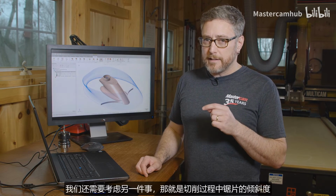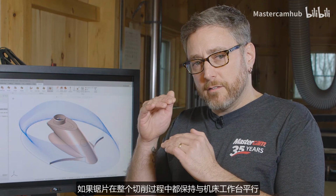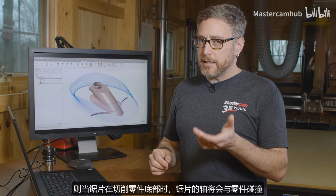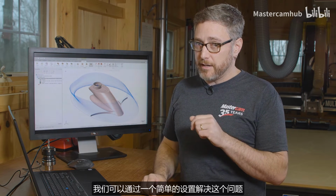There's one more thing we need to take into consideration, and that's the tilt of the saw. If the saw remains parallel to the table of the machine during the entire cut, then when it gets to the bottom, the arbor of the saw might collide with the part before it's able to fully cut the selected geometry. But we can address this issue with one simple setting.